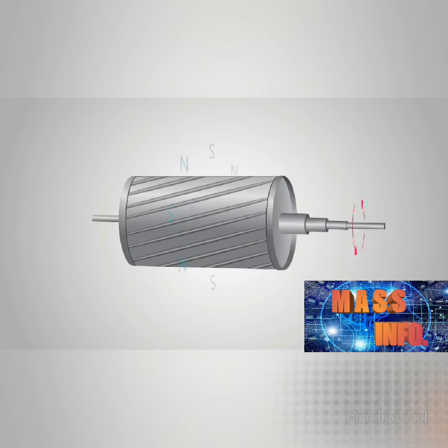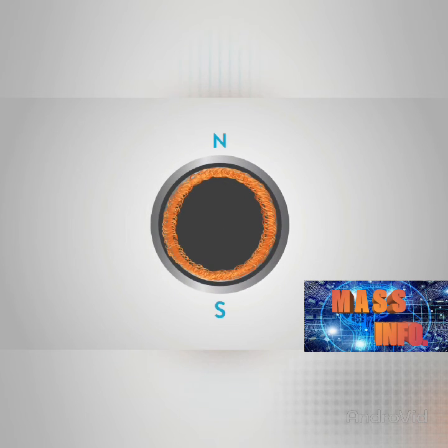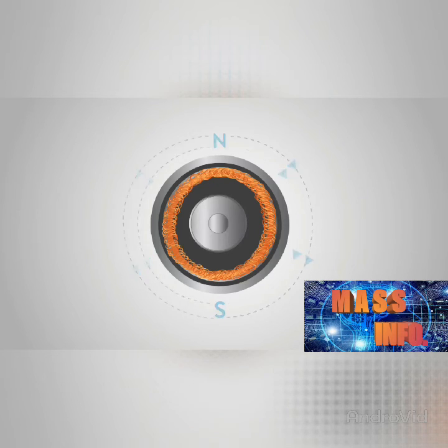Most induction motors contain a rotational element, the rotor or squirrel cage. Only the stator winding is fed with an AC supply. An alternating flux field is produced around the stator winding with the AC supply. This alternating flux field revolves with synchronous speed.